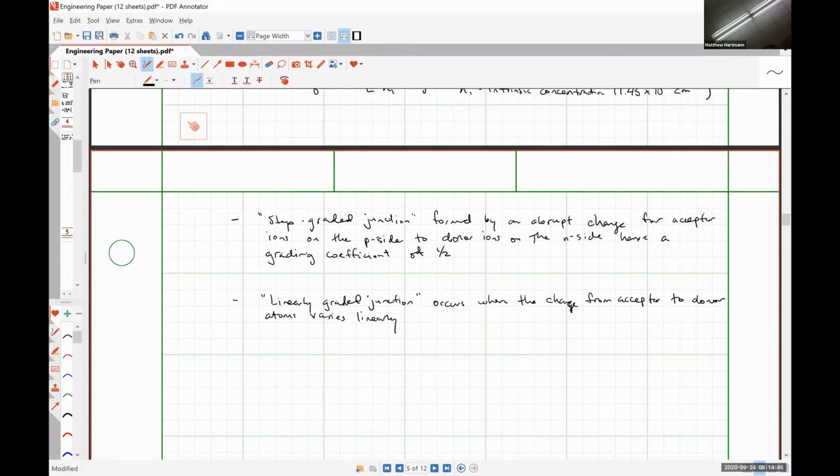It causes diffusion of the dopants, so we see that even if we've done ion implantation to force the junction to be as close to step as we can make it, when that diffusion occurs, there's a region where things kind of mix.